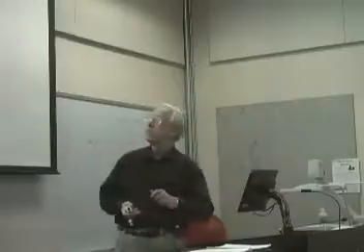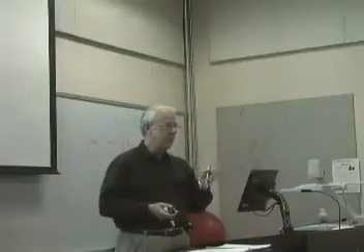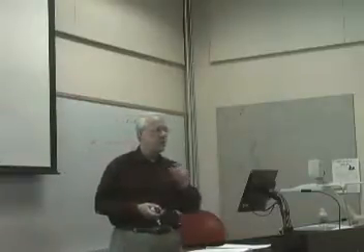Oops, let's go back. If I wanted to go to quadratics instead of linears, this is what I would look for. I now have 8 nodes. Why would I have 8 nodes? 3 per leg, 4 legs. So I have a total of 8 nodes. That's called, by the way, a serendipity element. It's called serendipity because it defines just the boundaries. If I throw a node right in the middle of this thing, then I would have 9 nodes, and those are called Lagrangians.